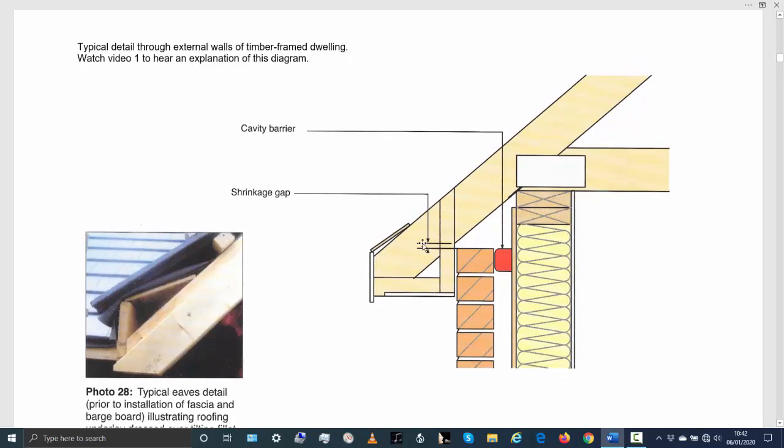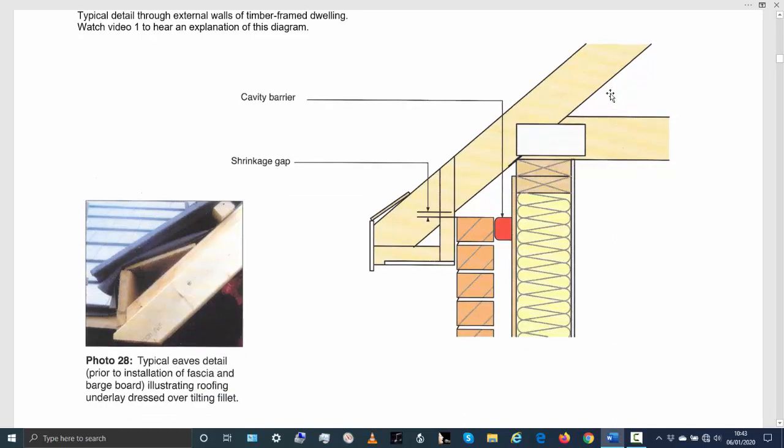That's a two-dimensional cross-sectional view. So you have your internal timber stud-work here, and that's actually the insulation that's shown there between the studs. You have your cavity, 50mm cavity, and then your external leaf, again shown in brickwork, but yours isn't brickwork, yours is actually masonry. So that's what your roof detail would look like.